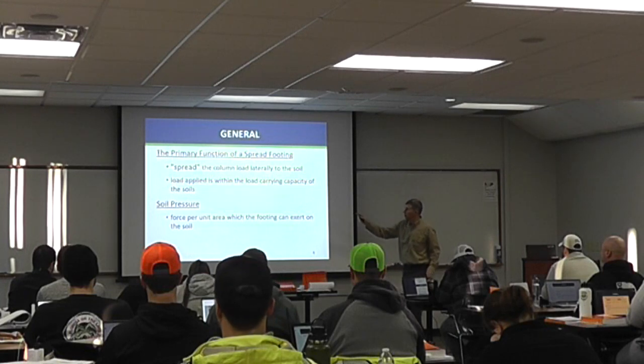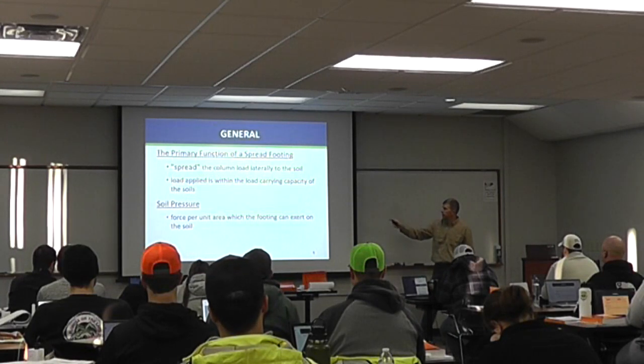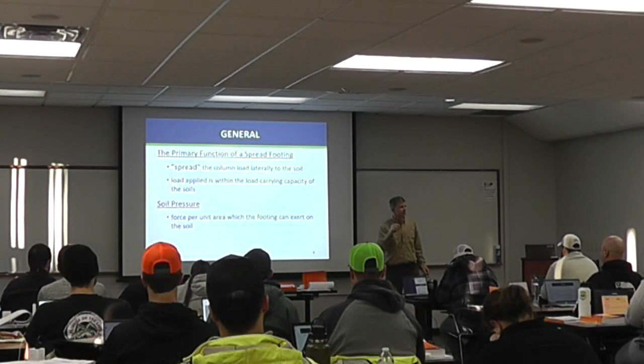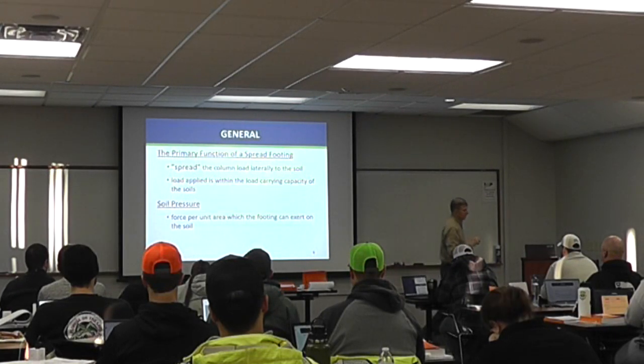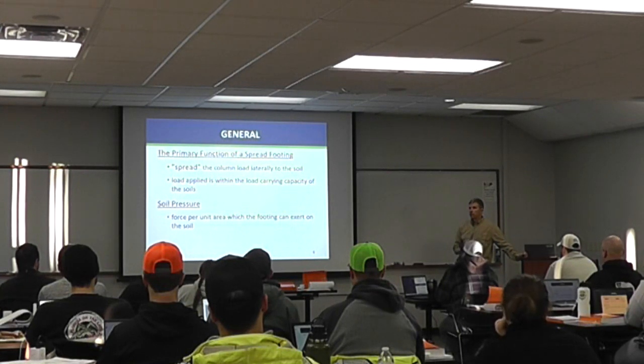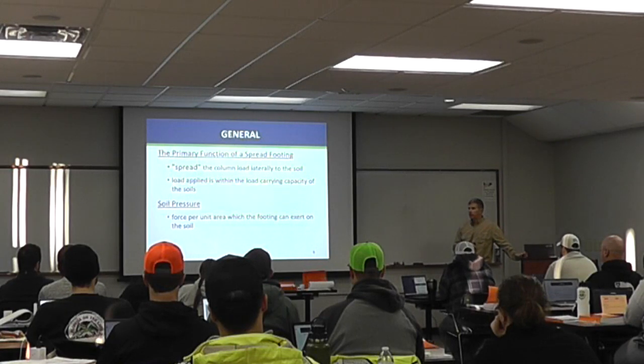So they spread the load, and it needs to be within the load carrying capacity of the soils. As we already have heard, you get something like bedrock, it's very stable. It can take an awful lot of load. Well, granular soil can too, sometimes. But there's other soils that are pretty weak, so we just need to be aware of what that is.